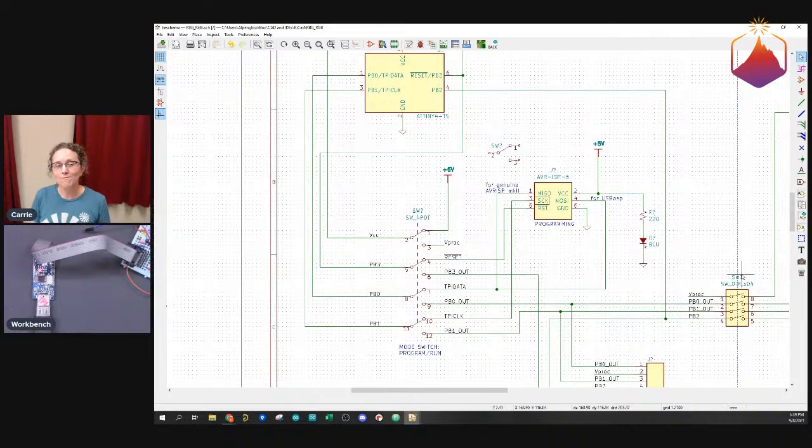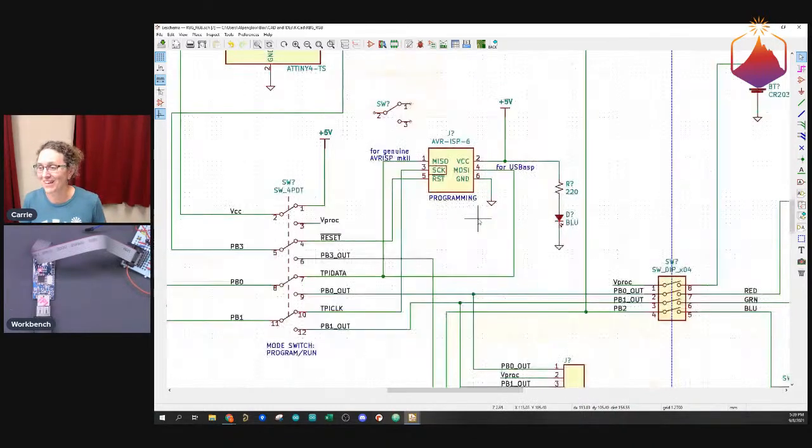Then finally something took me to a schematic of how you hook up a USB ASP. And I realized that the pin that they were using for the bidirectional data was the opposite one of the one that the AVR ISP Mark II is using for the bidirectional data.